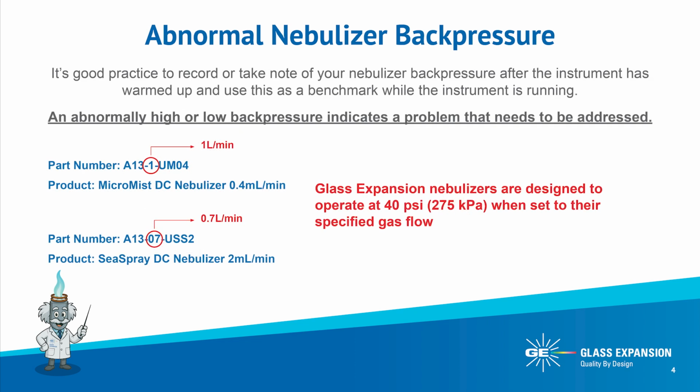It's always good practice to note your nebulizer backpressure once your instrument's warmed up and the ICP is running smoothly. That number will serve as your benchmark, so if it ever significantly deviates from this reading, you know there's an issue that needs to be addressed.